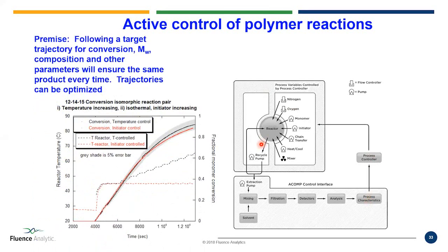So here's an example of a polymer characteristic, just conversion, to be simple. And this conversion versus time of a simple acrylamide free radical reaction, this black path was made by raising the temperature incrementally, and that speeds it up. And then we backed off, and we did this manually. We had an engineer, and we said, Natalie, keep the temperature constant, 45. Now feed in initiator, just like a computer game. Follow that path just by feeding an initiator, because that will speed up the reaction just like temperature does. And you can see she did quite well. She stayed within a few percent of the trajectory.